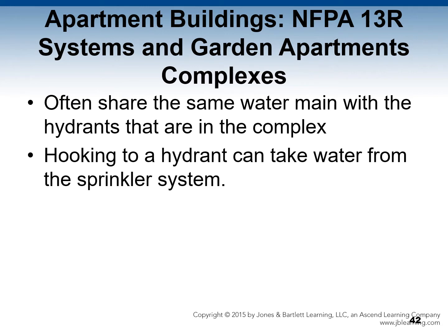NFPA Standard 13R, which discusses systems in garden apartment complexes, states that they often share the same water main with the hydrants that are in the complex. Hooking to a hydrant can take water from the sprinkler system itself.